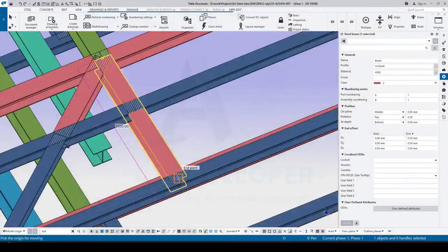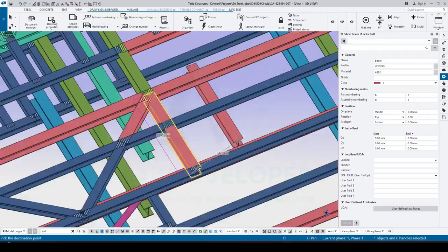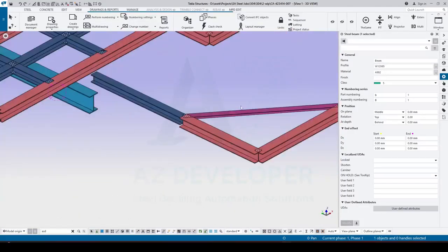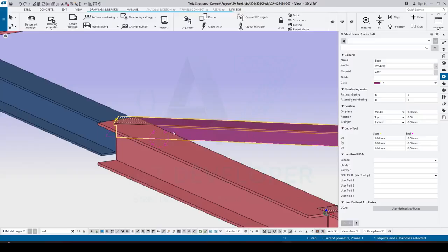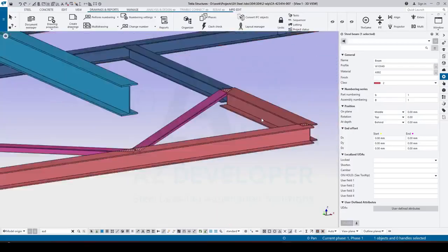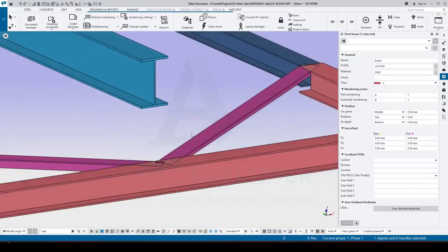Beams within a 50 mm tolerance are treated as duplicates. If they're more than 200 mm apart, both will be created. For horizontal bracings, they need to be manually lowered, as they're created at the top of steel level by default.